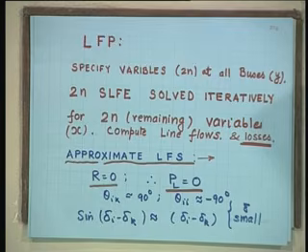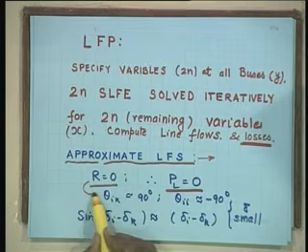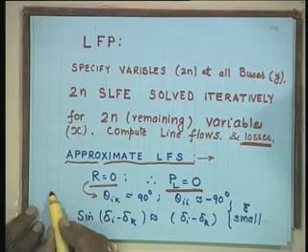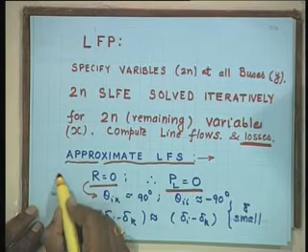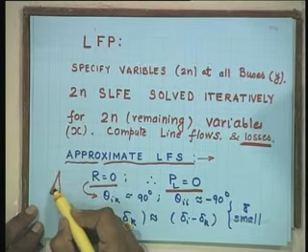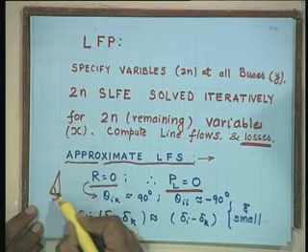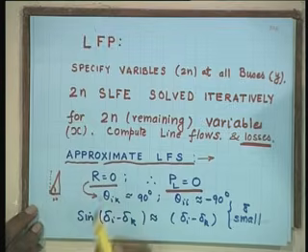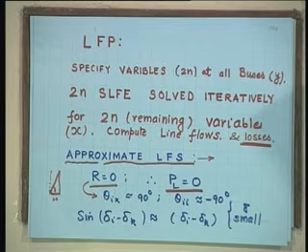And this R equal to 0 makes these both thetas 90 degrees. As it is, theta is close to 90 degrees. I told you R is very small, X is very high. So this angle is already close to 90 degrees, but when R becomes 0, then the angle becomes exactly 90 degrees. And sine of delta also becomes equal to delta when delta is small. This we have already talked about earlier.